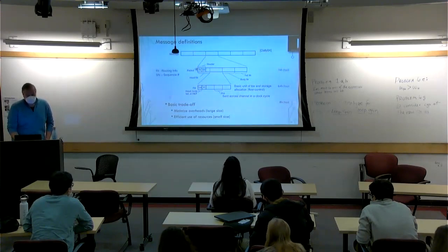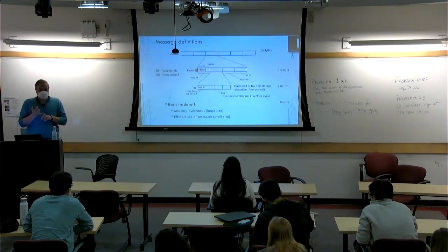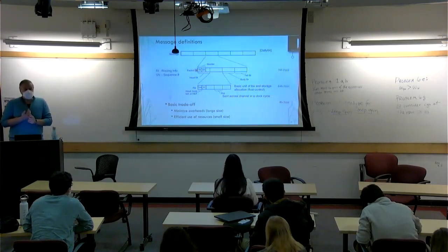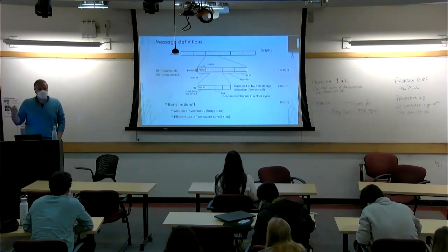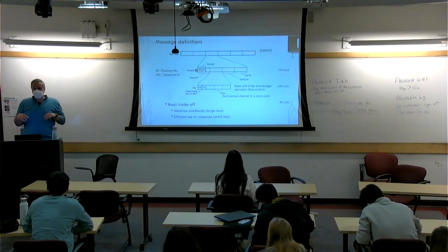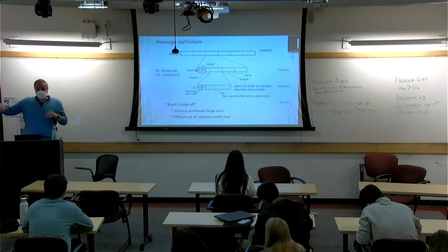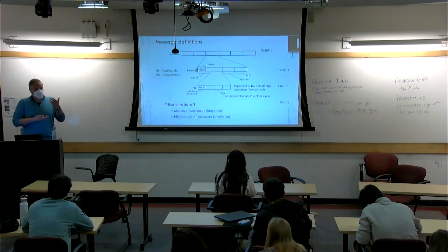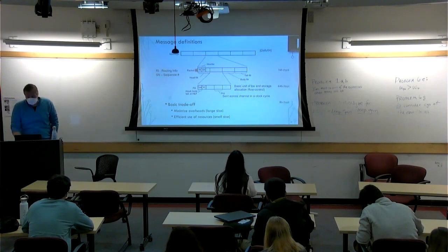The first flit will be the header flit. That one tells you where you're going. So it's routing information embedded in the flit. And also the sequence number, right? Because this packet has some sequence in the message. So for you to be able to assemble the message, you need to know the sequence, because these packets, depending on your routing algorithm, may be arriving at different times. Right? So something at the other end needs to track which packets have arrived and then reassemble the whole message, in case the packet is not your message, right? So there are those cases as well.